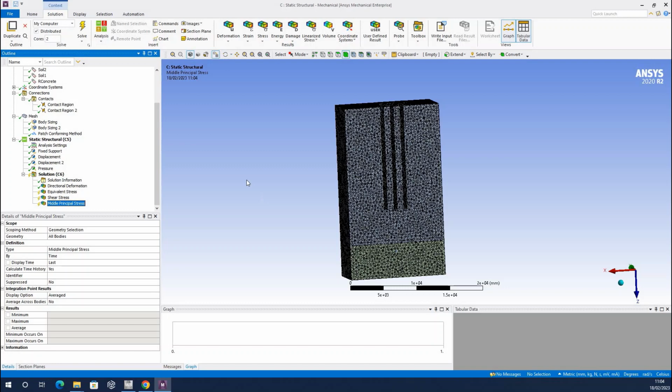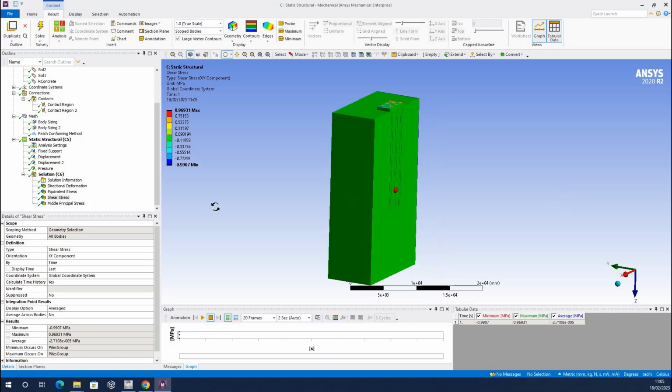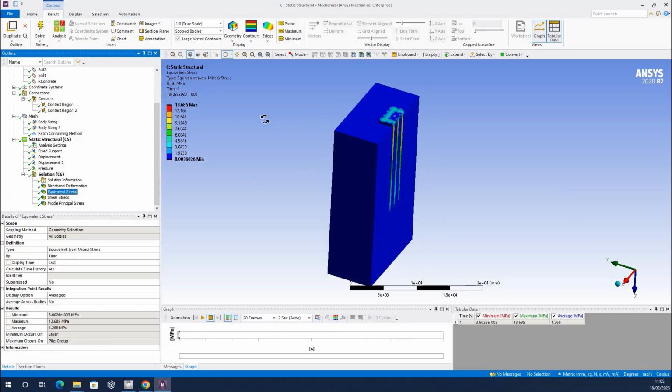And what you are going to notice now, once I click solve, is that the solution doesn't take a lot of time, because actually the model is already resolved in terms of displacement. So it's very easy for the software to resolve the stresses and strains, because the software just applies the constitutive equation that allows it to calculate the stresses in function of the strains, and the strains in function of the displacements. So using explicit expressions, it is relatively simple to find these solutions.